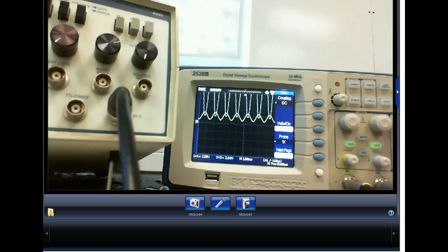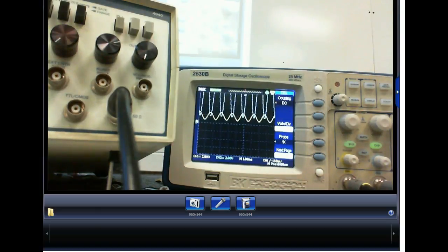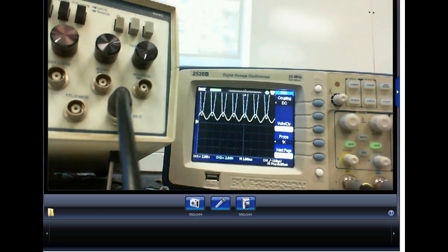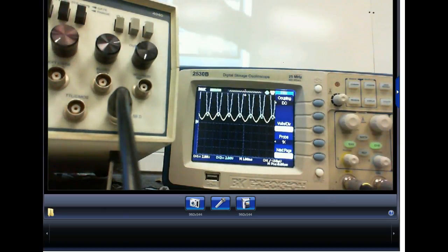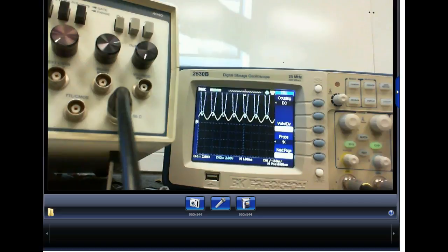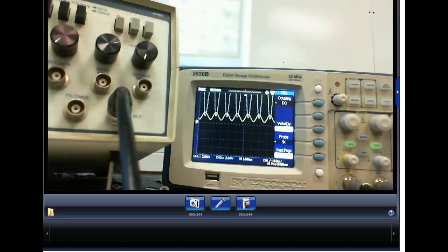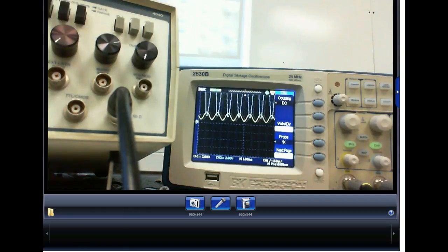So if we use the right size capacitor, then one of the things a capacitor does, once it charges, it blocks DC. So what it does, it lets AC come in and couple in with the base bias, right? You understand? And then it lets this AC superimposed on DC out here. It allows us to bring it out of the amplifier. So all I'm doing is just moving on to the other side of the capacitors.